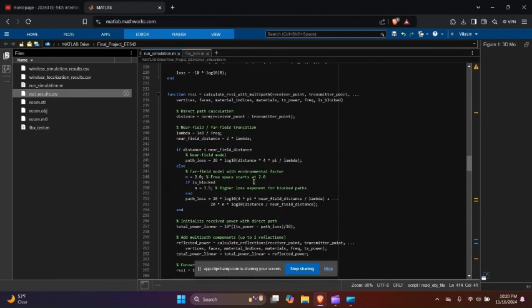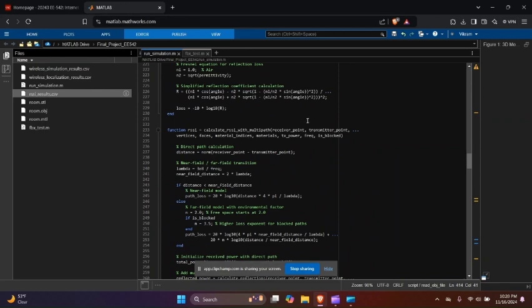Yes, so this time it is much more sophisticated. It calculates the RSSI and assumes a multi-path scenario too. It does not just assign a 30 dB path loss for reflected rays. It accurately calculates how many reflections it has, and then calculates the path loss. So that is one more additional layer of complexity this time, right?